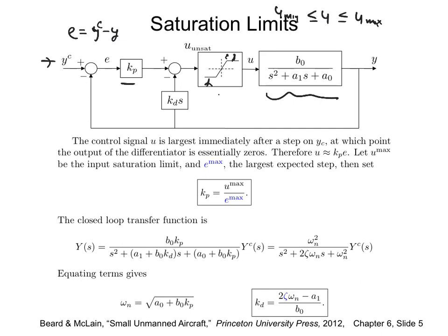And how do you choose your gains for that? So if you see, our U is equal to Kp times E plus Kd times E dot, right? That's the basic input. So your input is proportional to the error and proportional to the error rate. So at time t equals 0, when I'm commanding 35 degrees, there is no roll rate. So that means your E dot is 0. So you can cancel that part. You're remaining with this part now.